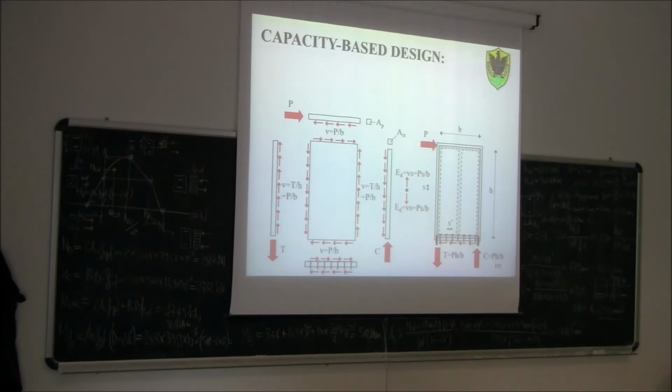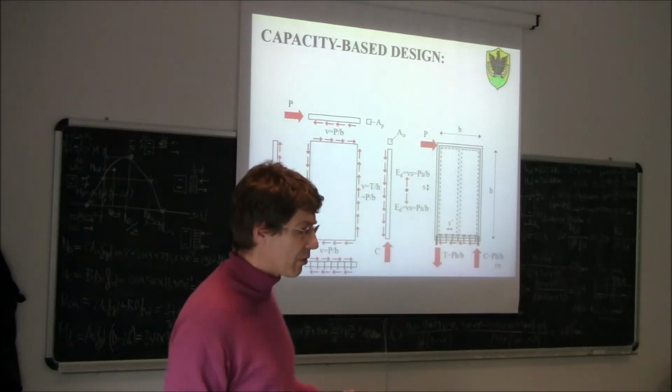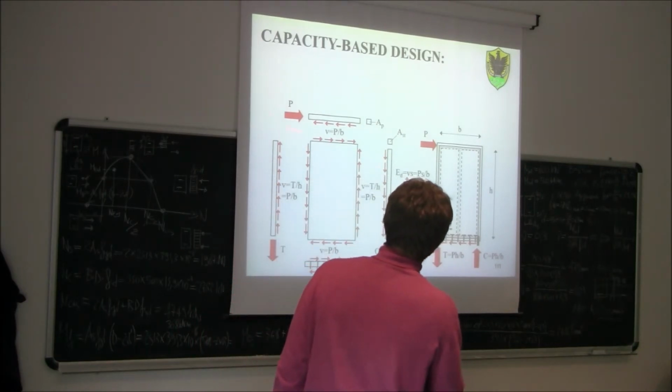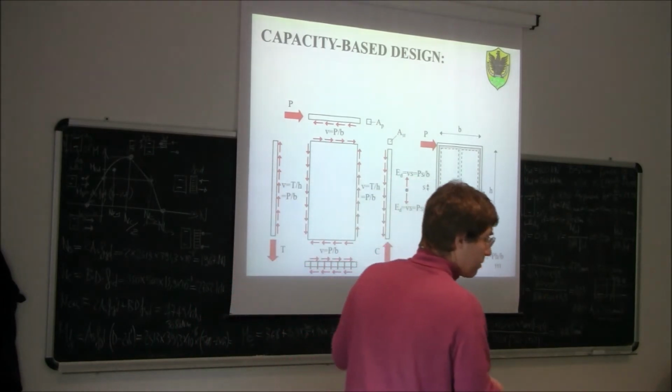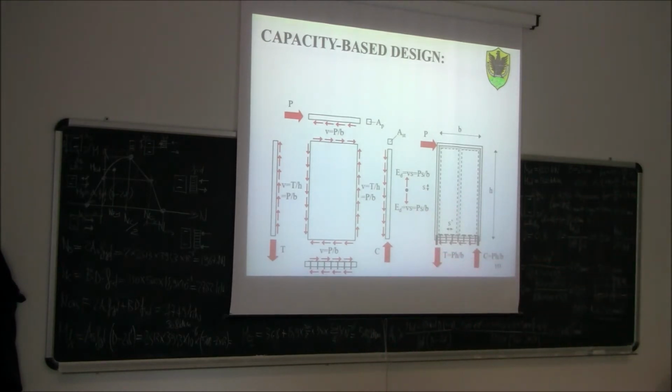So when it comes to designing a structure like this, we will calculate the lateral forces due to the earthquake using the design spectrum, which is the elastic spectrum divided by the Q factor equal to 5. Then we design these nails for this spectrum, and all the other members will have to be designed for the overstrength of this nail. So once we have designed this, we need to calculate another force, which is in equilibrium with the actual strength of the nail amplified by the overstrength factor.